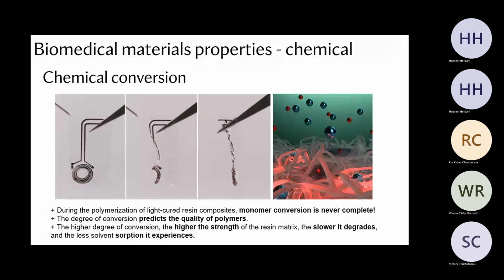In those cases, we actually intentionally want to dissolve the polymer with the solvent to make it less stiff, which I just explained is one way we can modulate the stiffness. But unless it's that case, we never want to have uncured or half-cured parts. We always want to have fully cured parts. But in other realms of what we use, for instance, in biodegradable materials, we actually engineer the material to degrade gradually, so that's something that's actually intentional.